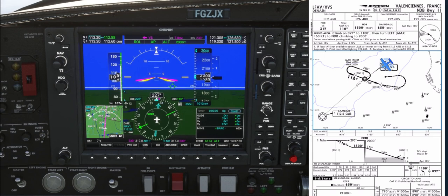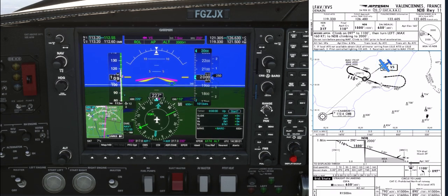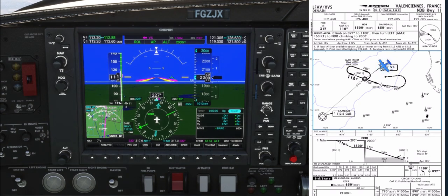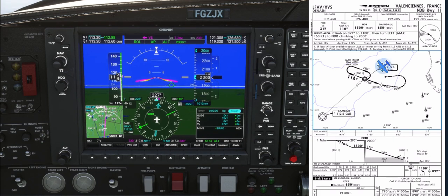Of course, refer to the holding module. As we are approaching the holding facility, we apply the holding preparation procedure. 1. Reduce the speed to holding speed. 2. Check the facility frequency or holding waypoint is the right waypoint. 3. Check that the bearing 1 is set on the holding facility, ADF, VOR or GPS, here, ADF. 4. Set the CDI tail of the needle on the holding radial. 5. Compute the entry.